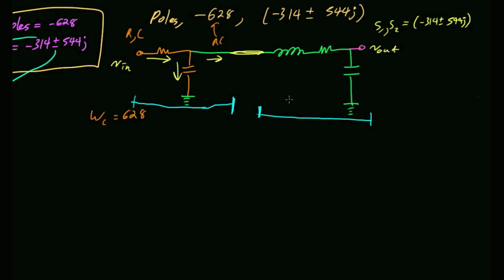What would be awesome is if we had a way of saying, okay, I need a pair of poles at this location, this circuit makes it for me. And I can daisy chain whatever I want after it, and that's not going to affect this circuit. So I need a way of separating these circuits so that they don't affect each other. Buffer. That's one way I could do it. Everybody remember the op-amp buffer? So one solution,